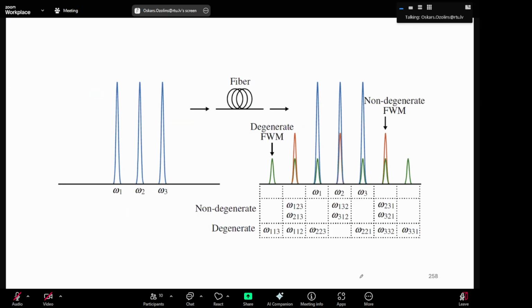And then there's one more, which is four-wave mixing, and it's rather bad if you, for example, have zero dispersion in a fiber. It was a very hard lesson in Japan when WDM systems were installed. They thought, okay, dispersion was the problem, so they decided to design a fiber with zero dispersion in the WDM system, and it created very good conditions for four-wave mixing, for Kerr effects.